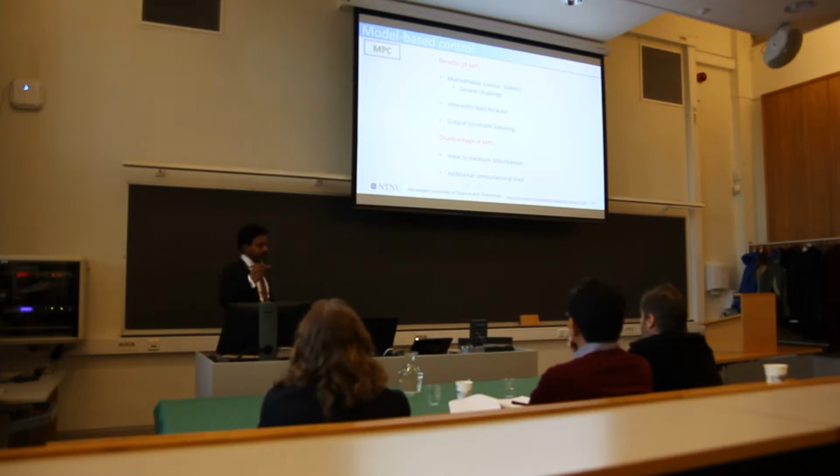So you have to meet those constraints, and with traditional PID it is a bit hard to do. So that's where it also contributes, where you can predict what specification you want to produce and you act already accordingly ahead in time. But there are disadvantages of MPC.